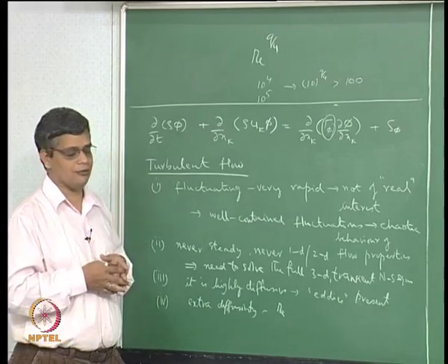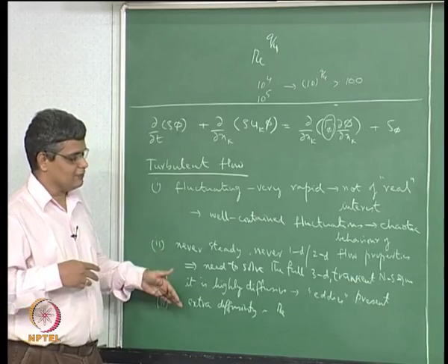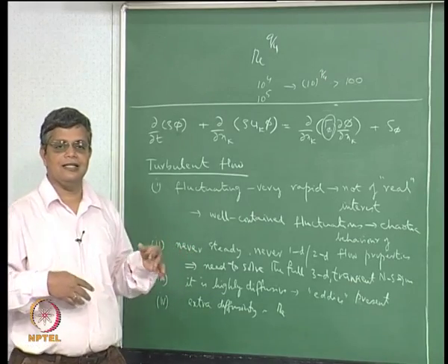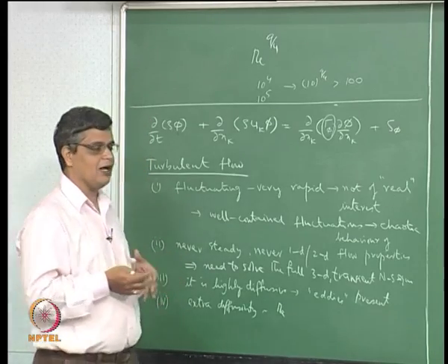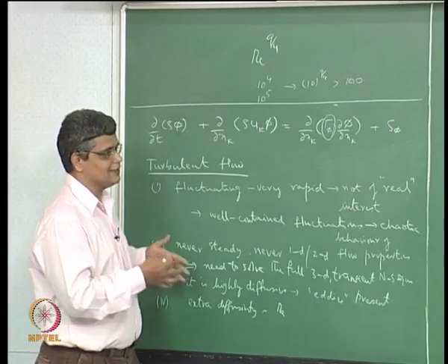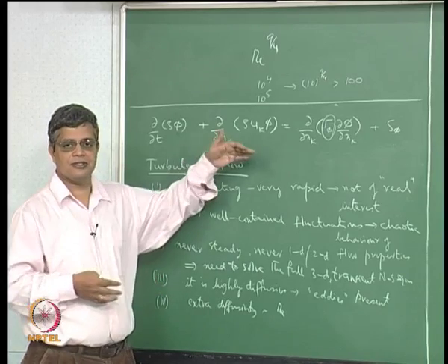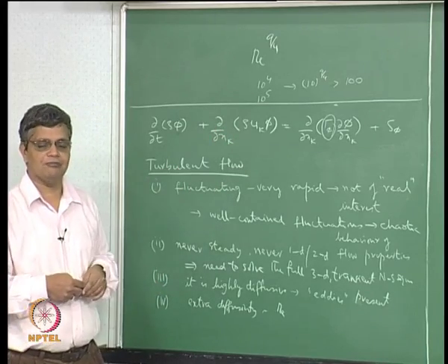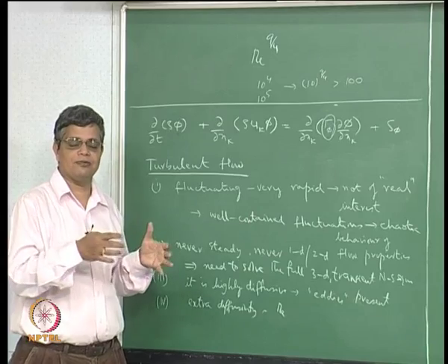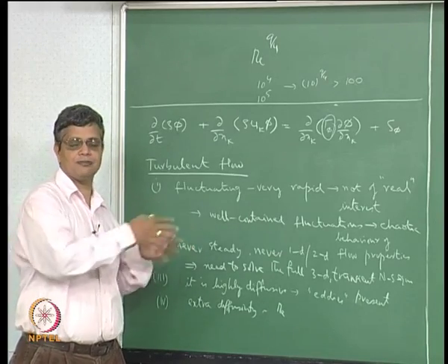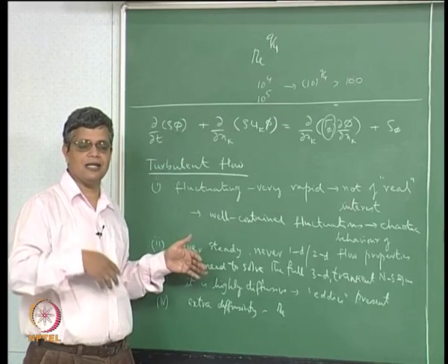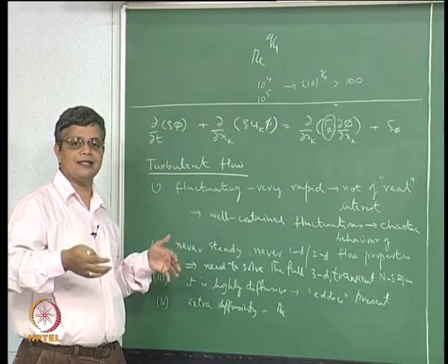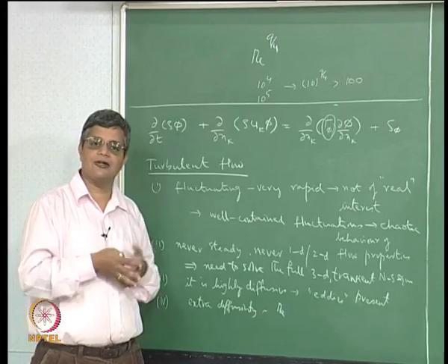That is in simple flows. So what that means is that if your friction factor is increased by an unknown amount and by a large amount, unless you know what that increase in the friction factor is, you will not be able to size your pump properly. Okay, the pump that you say requires so much horsepower, say 1 horsepower, based on laminar flow calculations may actually be requiring 10 horsepower or 100 horsepower.